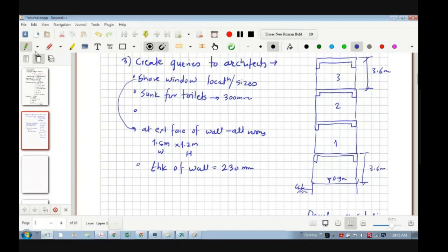Now I found that through architectural measurement, मतलब AutoCAD में measure किया मैंने 230 निकला है. You should verify with the architect कि ये 230 mm है. Now see, मेरा question ये है इसमें अलग से. First of all, I measured it, but I have seen that many buildings are having wall thickness as 150 mm. I think all of you know this. Yes or no? Most of the times in buildings we have 150 mm thickness. Now this architect is asking for 230 mm.